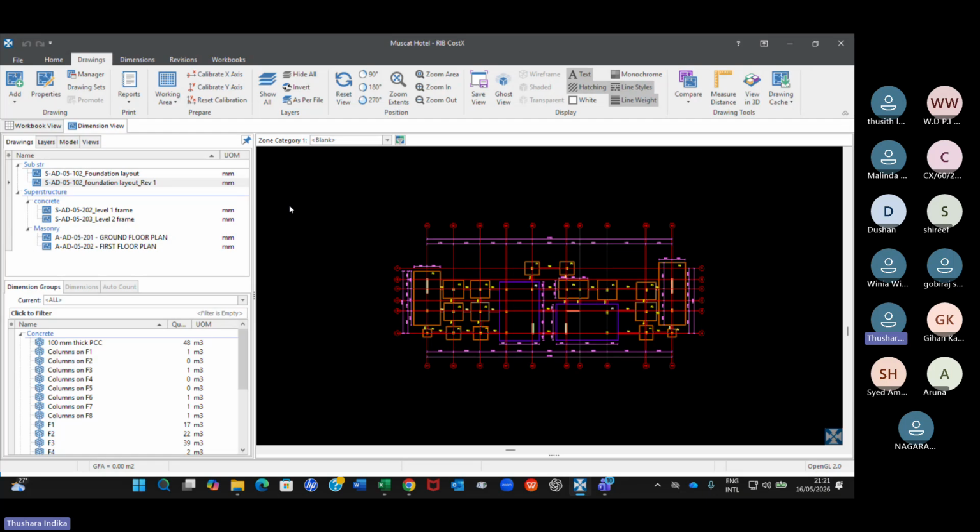And even if they have clouded, you're not 100% sure they have clouded all the changes in a drawing. So that is a common issue that we face as consultant QS when you prepare BOQs, right? You are not 100% sure that the engineers or architects have captured all the changes in a cloud. Sometimes you can't believe it either.